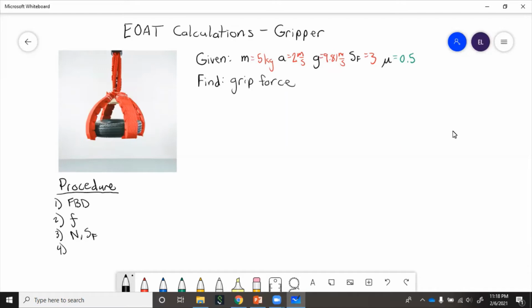Finally, verify with manufacturer. This is because certain manufacturers will be able to tell you if they have a gripper that'll work for your application, and probably also be able to recommend something that has the right throw size or number of fingers or whatever else it is that you're looking for.